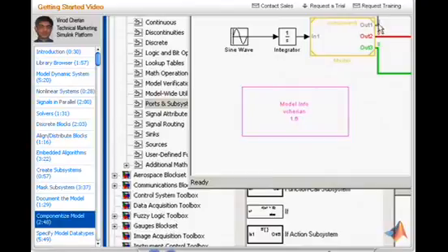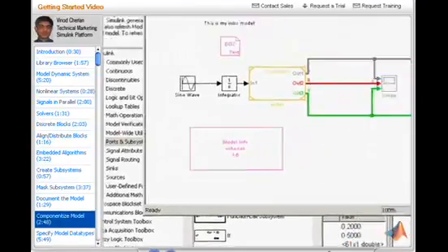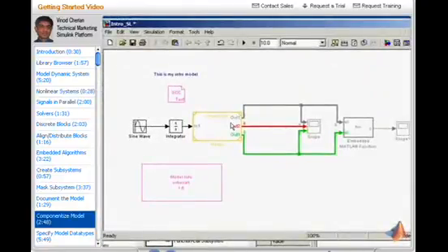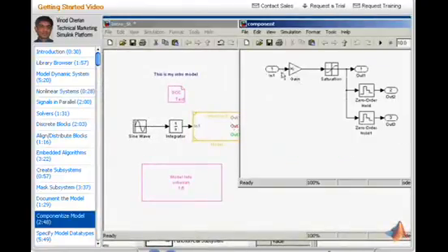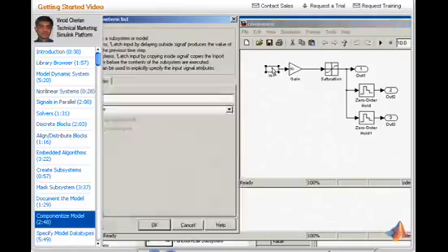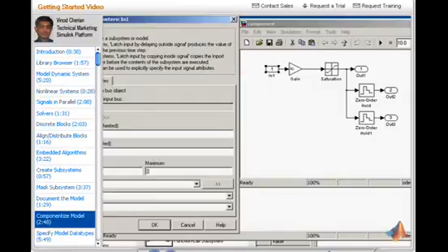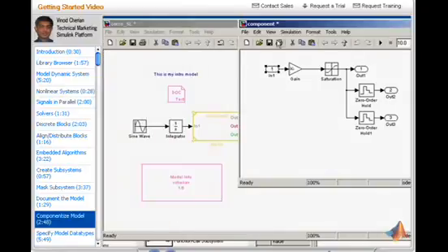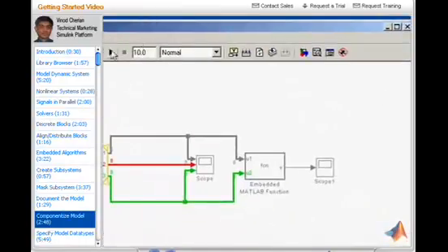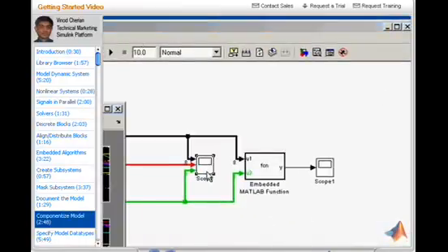As you can see, it aligns from a continuous time to sample time, and let's let this happen. If you double click on this model, you can see that there are no continuous parts in this model, and everything in this component can be run in discrete time. So what I'm going to do is force it to use a continuous sample time for the default import. I'm going to save this now, and I'm going to simulate this model. Let's look at the outputs, and this is exactly what the original system had as outputs.